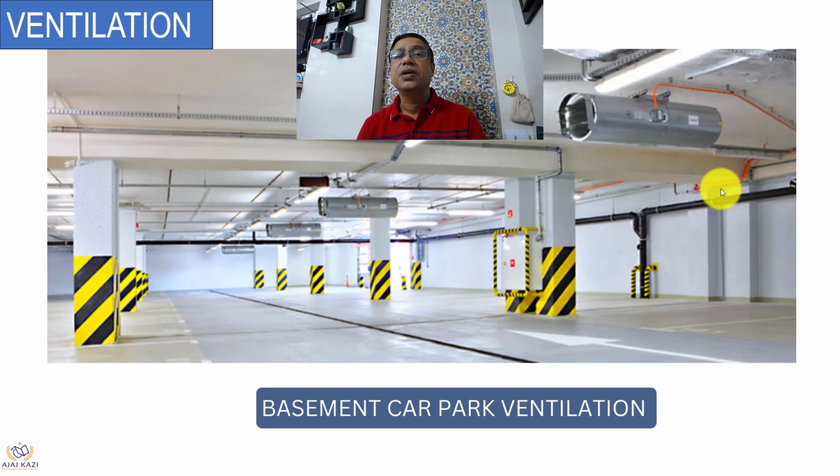But the same issue comes when we have fire in the basements. What happens in case of fire? All these fans are designed in such a way that they go to higher speeds and you evacuate the smoke fast. Remember, people die because of smoke more than the fire. So it is very important to remove the smoke from the zones.